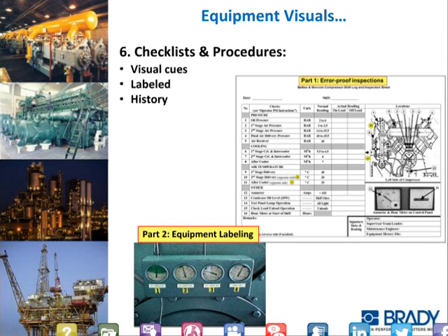in this history sheet whether the compressor was on load or off load, and there was a light on the panel that actually told you that. And then the diagram was just the diagram out of the compressor manufacturer manual, and the hour meter and the amp meter right out of the manual, dropped into this document. And then on the actual compressor, part 2 is down near the lower center. Every inspection point on the compressor was labeled to match the diagram. And you can also see the green gauge label that shows the allowable ranges.